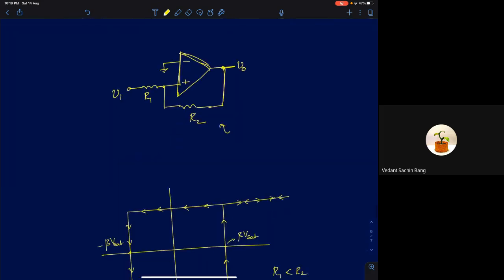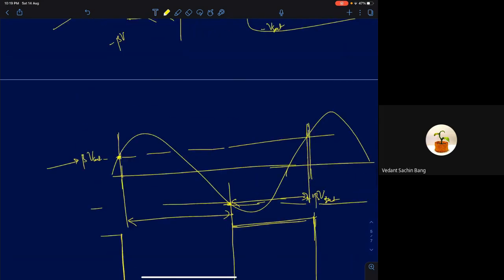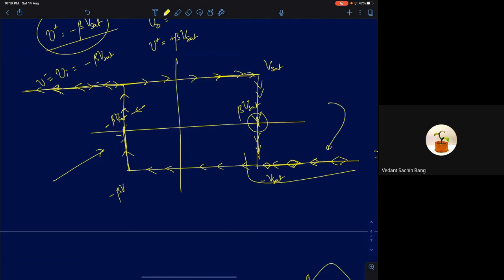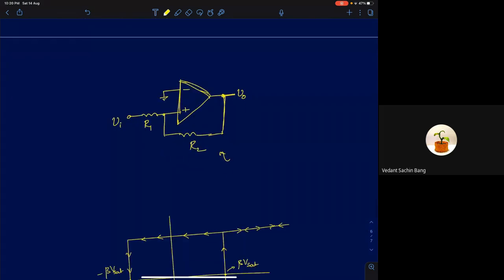We will now look at another way, of course, using positive feedback. So this is what we have shown here. This is an inverting Schmitt trigger. If you see, for positive values of input, you're getting negative output. So it's an inverting Schmitt trigger. Now I'll apply the input to the positive terminal itself, so there is positive feedback here. Now to this circuit, we will try to analyze it in the same way and draw its transfer characteristics.